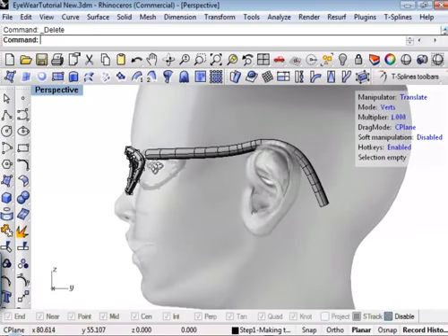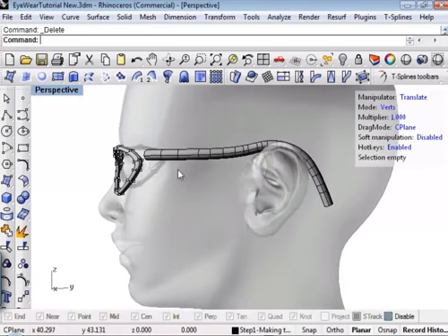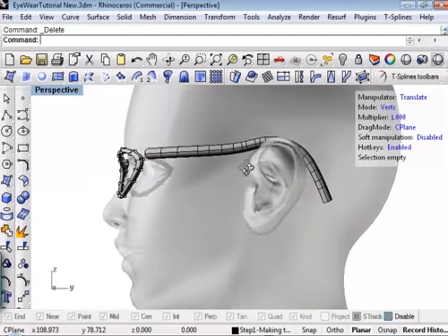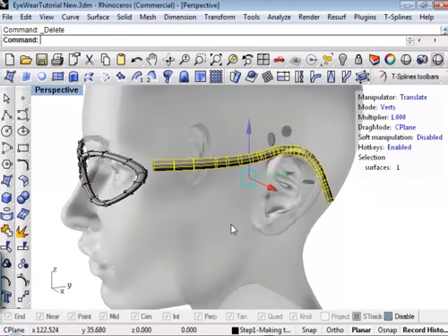The other thing that you'll notice is the curve from two directions tends to create a lot of segments and edit points and stuff like that in a curve. And there's way too much geometry going on here. One of the names of the game with T Splines is simplicity. If you can do more with less, that's what you want because you're going to get a smoother result. So let's go ahead and grab this.